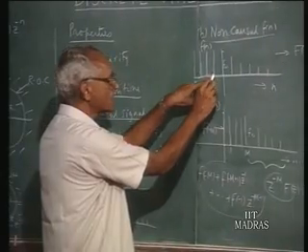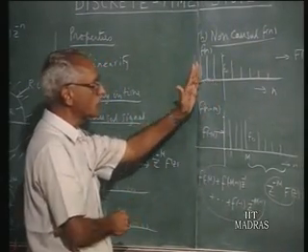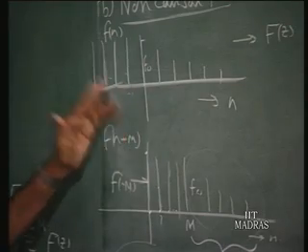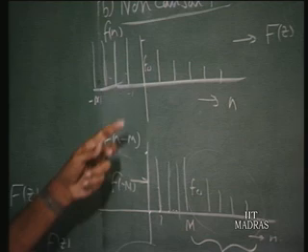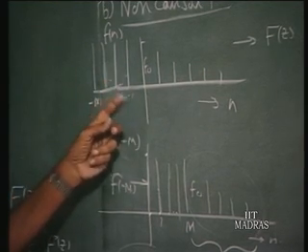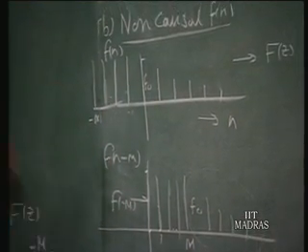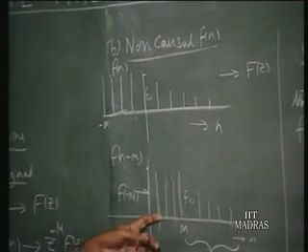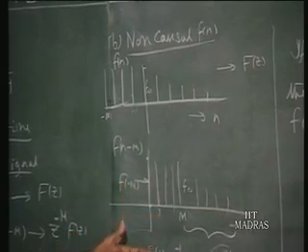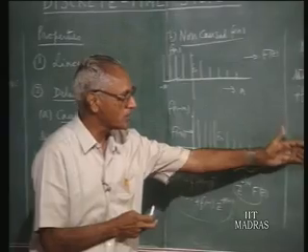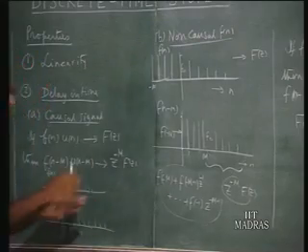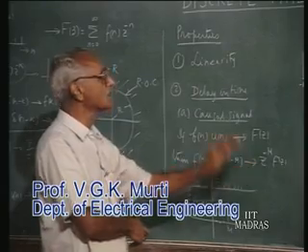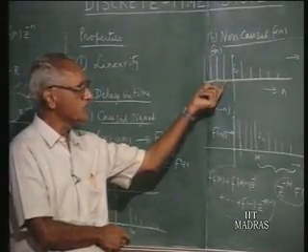So this is important because sometimes when you take difference equations, you are prescribed certain variables whose initial conditions are prescribed at minus 1, minus 2 and so on. That means one of the variables is said to have values at negative values of n, and therefore when you delay it, suppose y of n is said to have given values at minus 1 and minus 2, when you form y of n minus 1, y of n minus 2, you are delaying that. Those values come into prominence here, and you must take their values into account in forming the appropriate Z transforms. So keep this in mind. For causal signals, it is of course straight multiplication by z power minus m. For non-causal signals, you must take these values of the samples also into account.